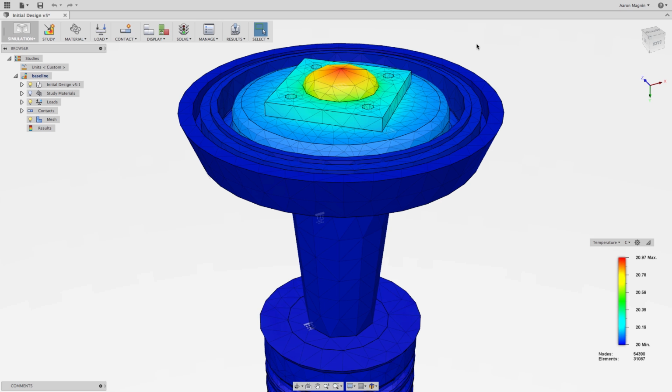It does look very blocky, and that is because I'm using these draft quality elements, the non-curve style. And when I'm looking at these results, I'm questioning them, right? We have 5 watts, which is actually pretty significant if it's concentrated. I mean, 5 watts without appropriate convection could heat up to infinity essentially.